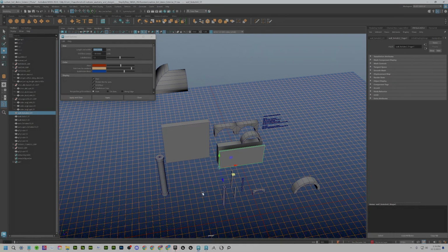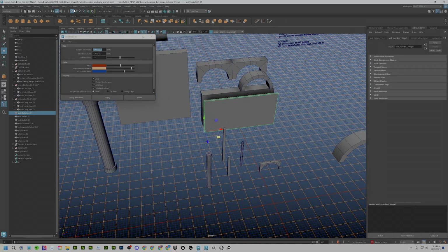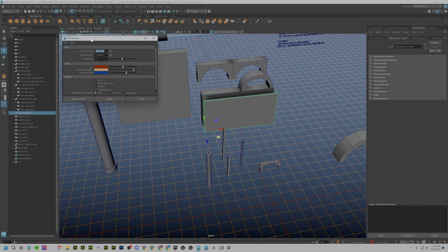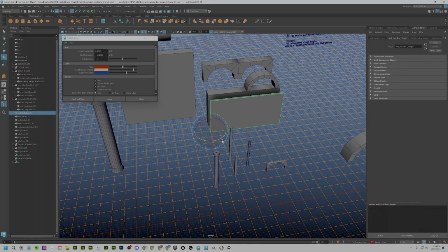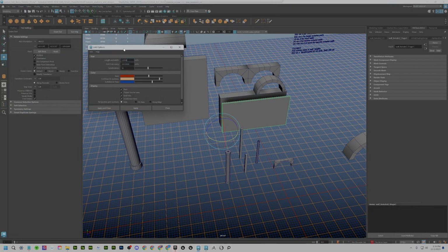So the grid snap, I leave that turned on for almost the entire time, and snapping again when you want to move things diagonally. If you move it and hold the J key down before you start moving, there it goes. You'll see that's going to let you rotate with even degree increments without having to go in and constantly change your increments.